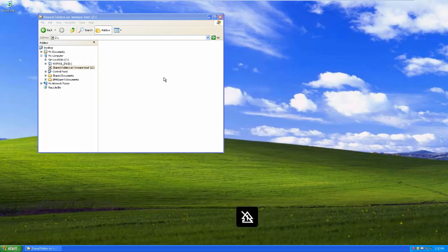So, like I mentioned, I always have a projects folder that's on my host, and I store all my project files in there. Now, keep in mind some software packages, for example, Factory Talk View, that's the Allen Bradley HMI software, likes to have its project files local on the virtual machine. So you'll have to remember for applications like that to back it up, make a backup file, and put that backup file into your shared folder so that it's on your host.